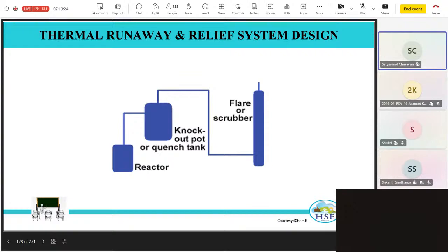Then you look at chemical compatibility aspects, using software and various literature. Then you do your screening studies using DSC, and try to understand the complete process, either in small steps or multiple steps, and understand the hazards through screening using DSC.